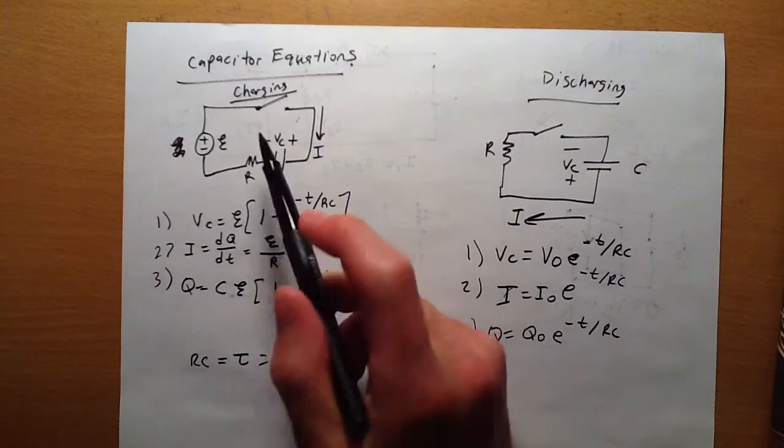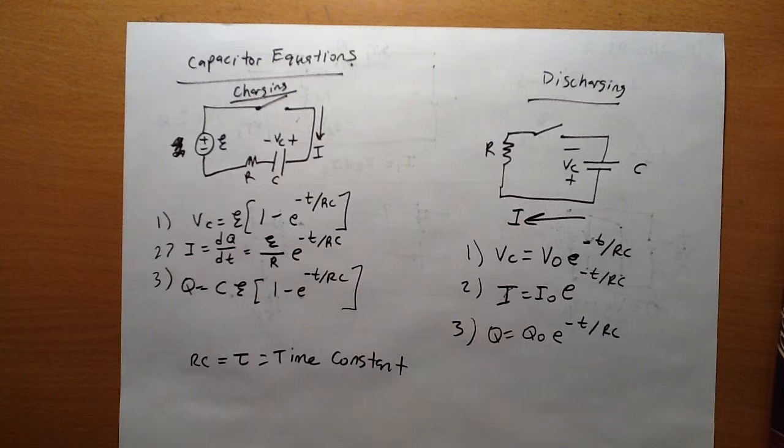That means in this situation, we have a capacitor that has no charge. We start charging it. At time tau, which we find by multiplying the resistance times the capacitance, the capacitor has 63% of its maximum charge. You might be tested, so just know RC, 63% of full charge.